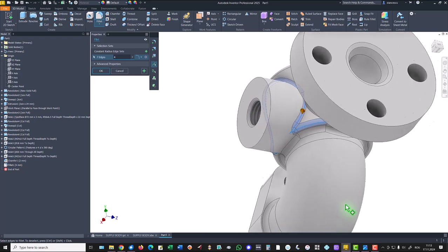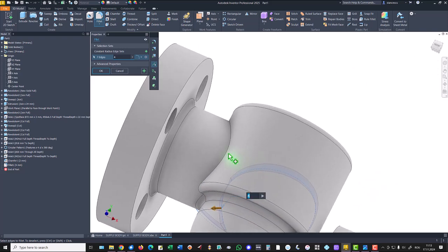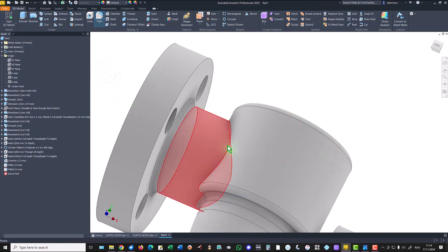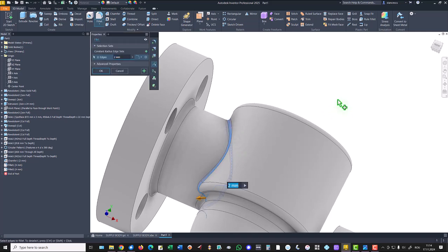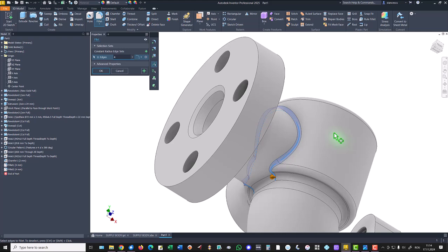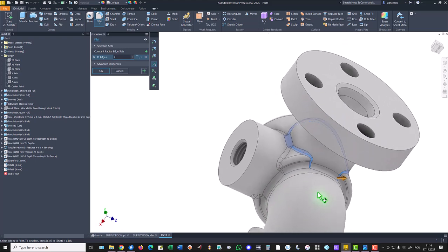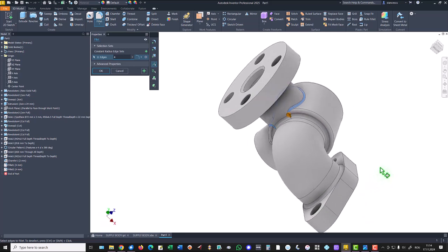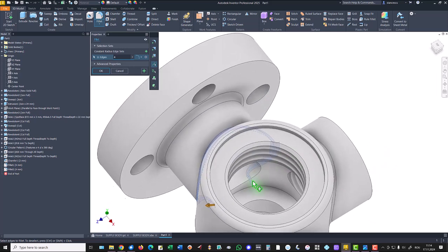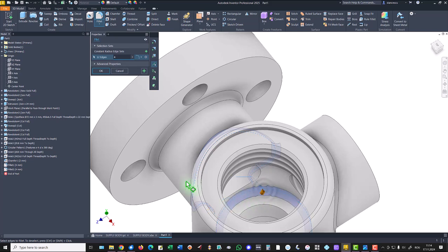Shift and disable. I try here. Once again is not accepted. Okay. Shift, 4 millimeters. You see, you have to apply a sequence of fillets to cover everything. This is the last. All of 4 millimeters.